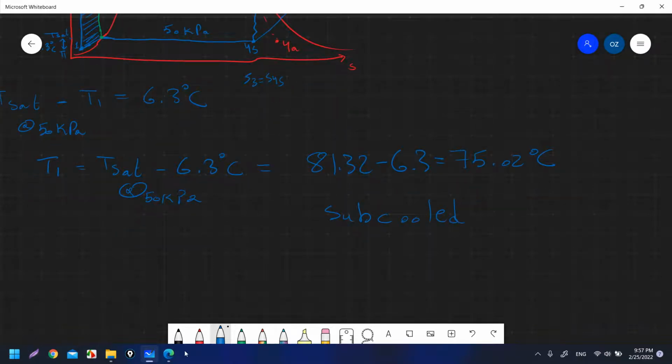State 1 is a subcooled state. We approximate the values of the properties to be equal to the saturated liquid values, and this is an approximation. Usually we have another term, v times (Psat minus P1), but this term is very small, so we cancel it and we approximate that H1 is equal to HF and V1 equal to VF.